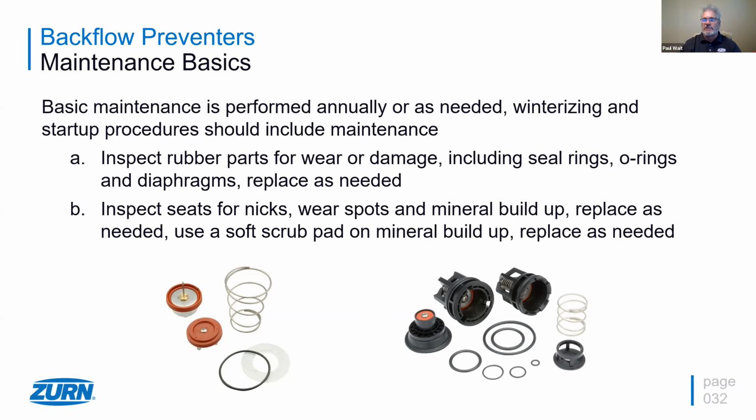It causes some disruption in the backflow preventer. Sometimes some of that particulate can blow right through the backflow preventer pretty easily. Or if you can get that relief valve to dump on cadence by opening and closing your number 3 test cock, you can get stuff to dump out, and you can clean out the valve that way. But generally in the wintertime, when you do winterization, that's the perfect time to get the backflow preventer inspected, replace any rubber goods, and then look at it and get it ready for the install for the season.